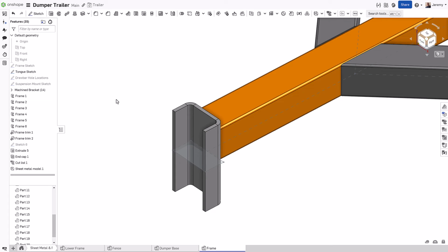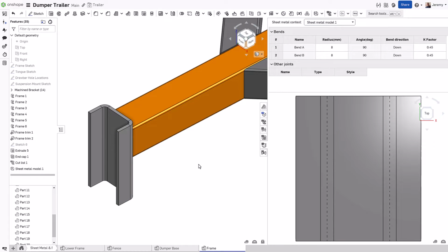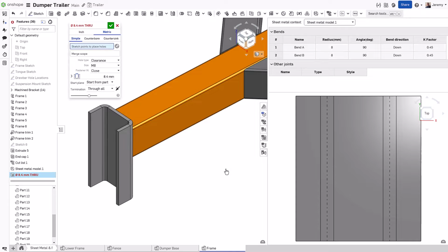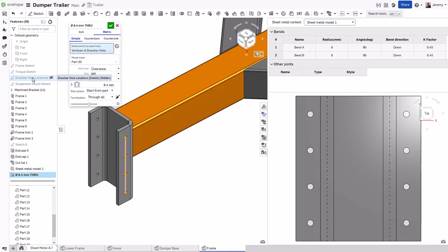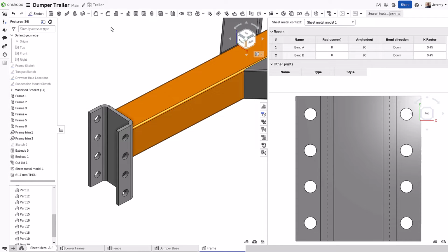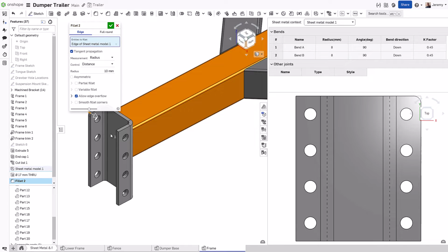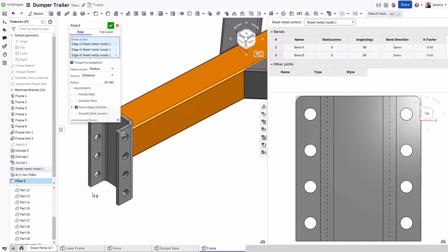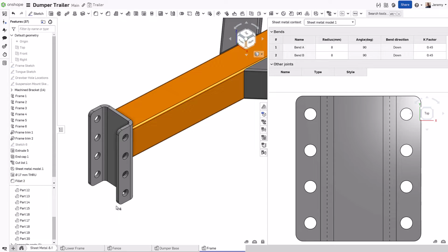However, as soon as a sheet metal component is created, its flat pattern can be viewed from the flat pattern pane. This flat pattern is a live representation of the flat pattern for the component, so as changes are made, they can be realized in the flat pattern in real time. Not just as features are added either, but even the previews of new features, ensuring you're designing what you want before you commit a feature change.